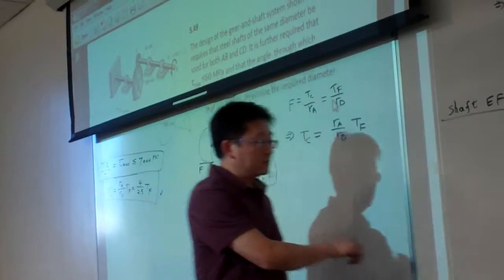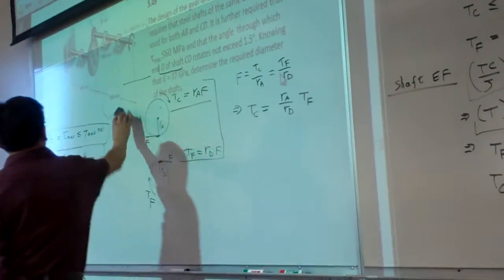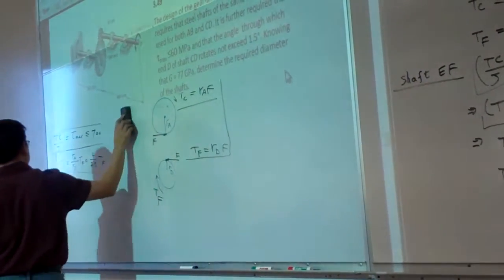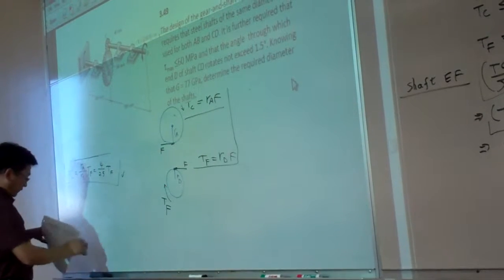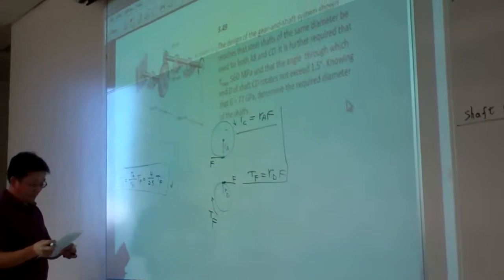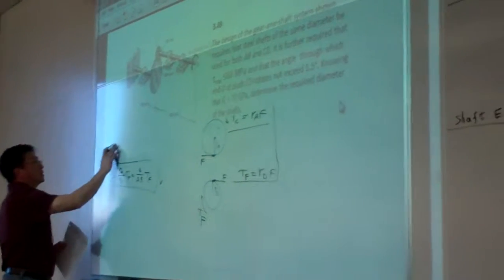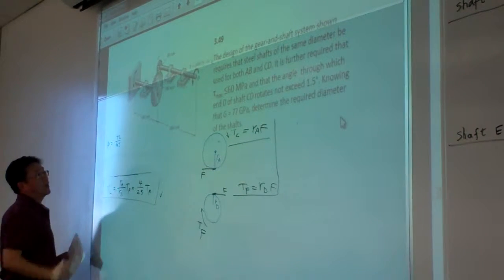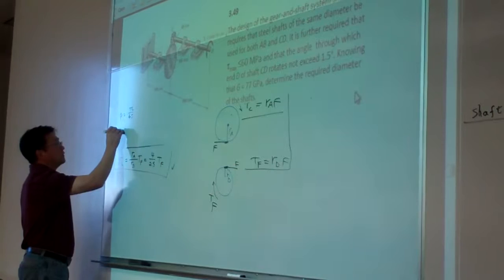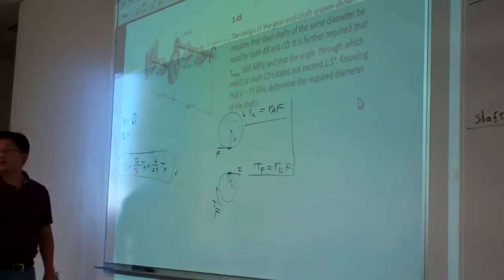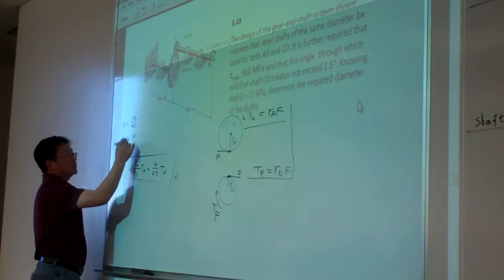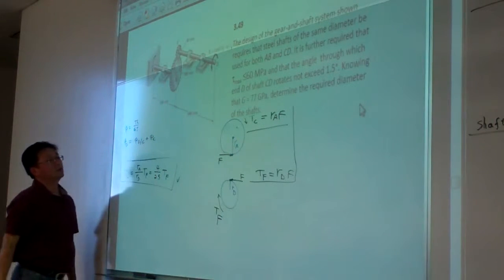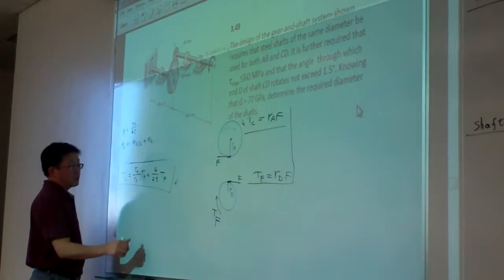So we can write down all the needed information here. The first one is the angle of the twist: phi equals TL over GJ. Also, for the angle at D, if we take the relative rotations, the relative rotation basically is phi of D relative to C plus phi C. Okay, and the third information we would need is this.